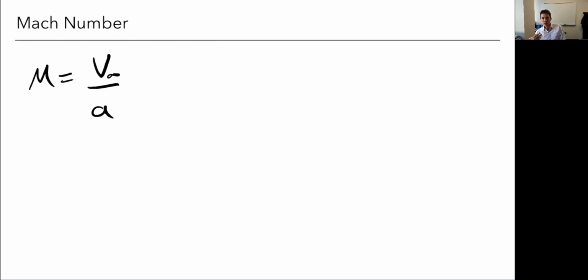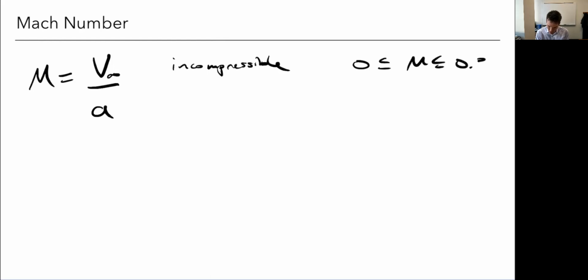But as aerodynamicists, we often use additional categories. These do not have accompanying exact breakpoints, but are just words that are used to help delineate things. I'll explain in a second here. So for example, we often will call flow incompressible. The real limit is in the limit of Mach 0, right? That's truly incompressible. But typically we would say up to about Mach 0.3.